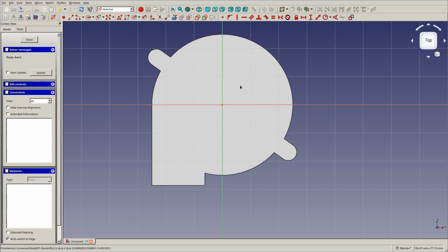So let's map a new sketch. I'm going to need to access these 2 points again, so I'm going to import them. And I am going to need a construction line connecting the two. And the center of the air intake is actually not centered with the fan itself. It's a little bit offset. So I'll make the circle first, and we'll position it just after.